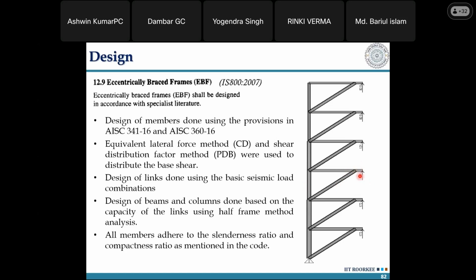So here is the case where a column tree has been formed. When you model it, yes, this model is unstable. If you give loading like this, you have to give some boundary conditions at each floor level. Now what I'm doing here is, this is a short shear link and the maximum shear capacity of the link element, the maximum expected value that your link element can give, including all strain hardening, material uncertainty, whatever expected value the code says. On that basis, I have to find out what forces I have to give.